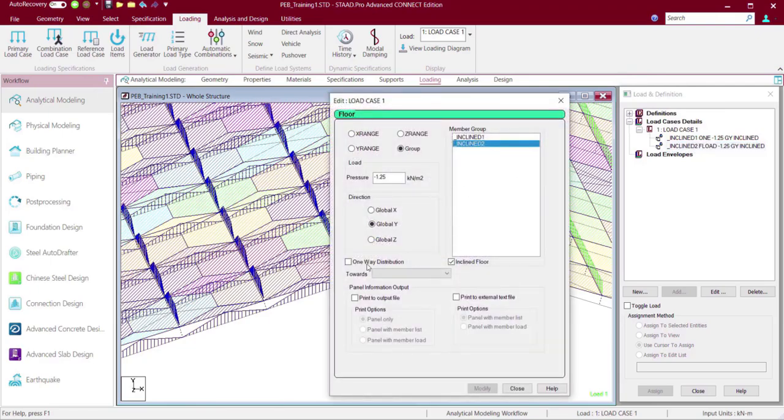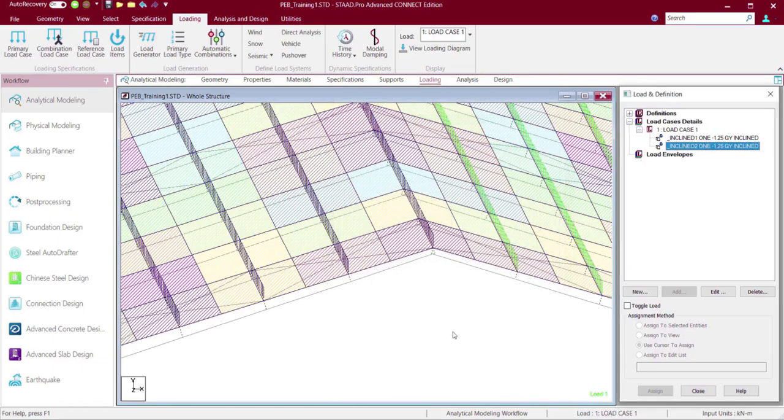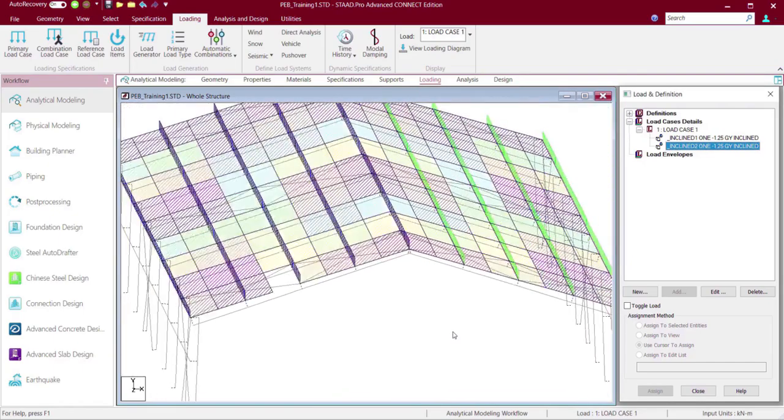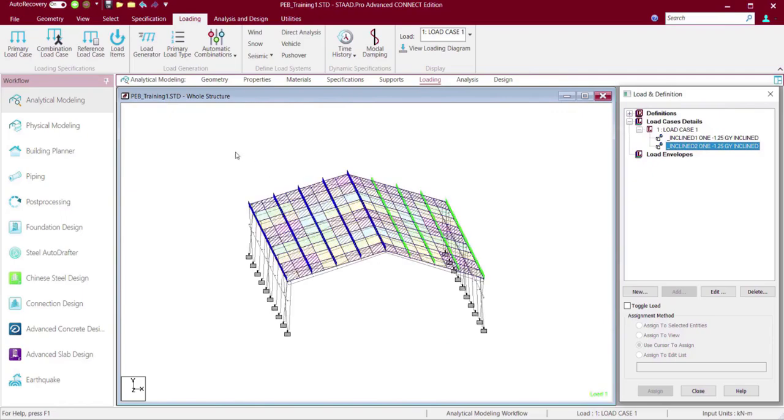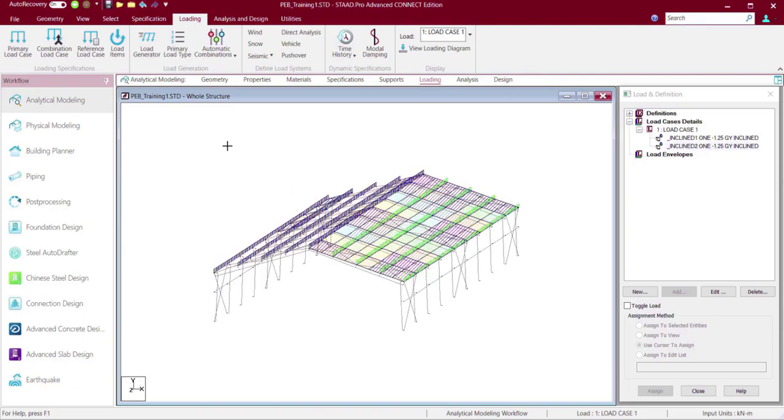Okay, so I have also modified the loading distribution as a one-way load distribution pattern for the other half. Now, several users do not use this procedure to apply the floor load on those purlins. They straight away calculate the load, because basically these loads are applied on some parallel members, and then these loads are generally acting as a member load.